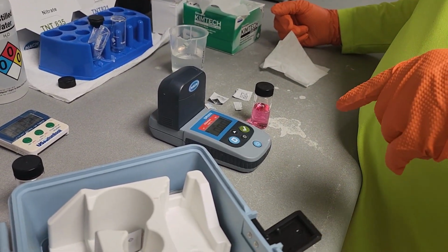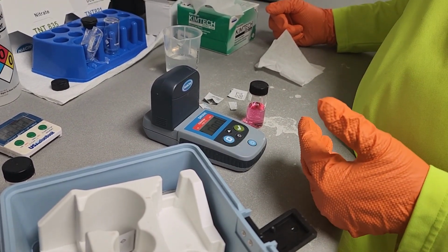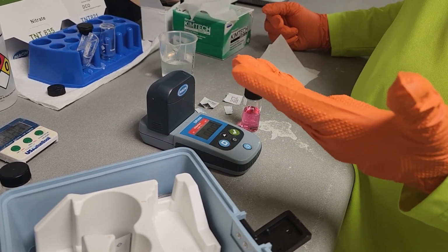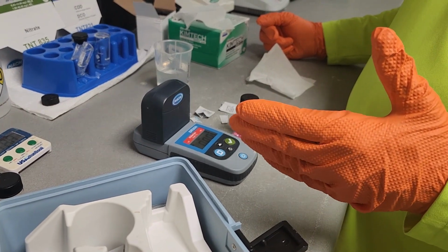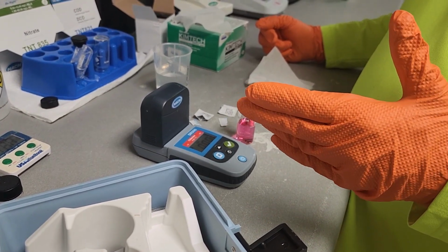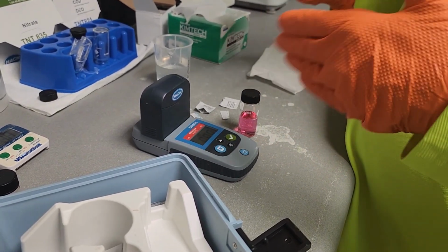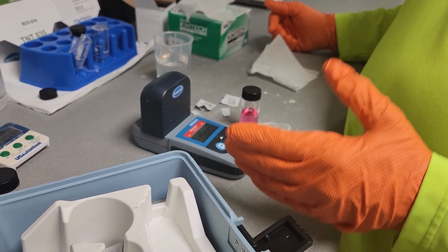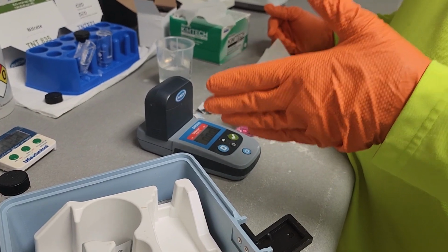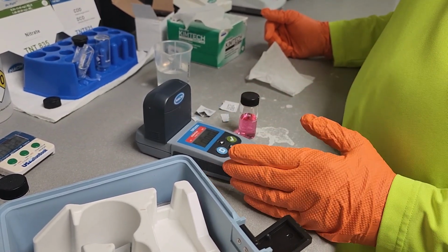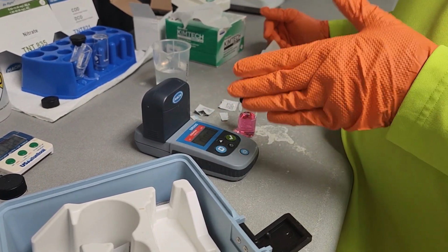So lately in our training program, in the most recent videos that we did, it's on breakpoint chlorination and chloramination. And a big part of breakpoint chlorination is to determine your total chlorine residual and your free chlorine residual, to calculate out combined residual. You know, we talked about the initial dose when you're determining what your breakpoint is. The initial dose of chlorine reacts with the metals in the water, oxidizes them, and that's why you don't get a residual right away.